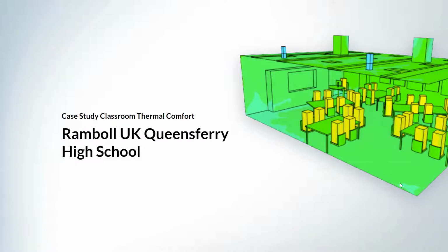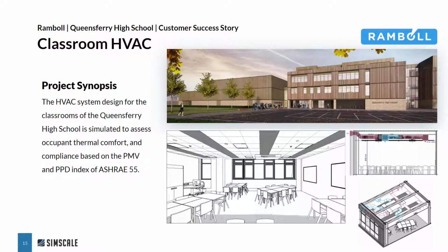The actual case study is a case study that we performed with our customer Ramboll UK on Queensferry High School. So what you're looking at on the right is a particular classroom that we considered for the thermal comfort study. A bit of background on what we're going to simulate: again, it is a particular classroom from this high school where we would like to see whether the thermal comfort is within the compliance of ASHRAE 55, which is based on PMV and PPD, as we have seen in the previous slides.